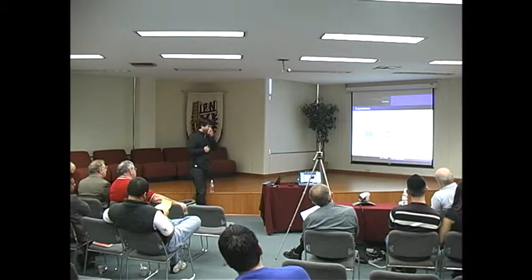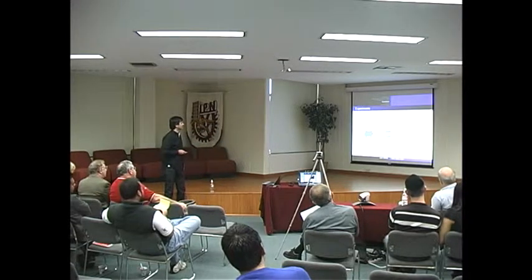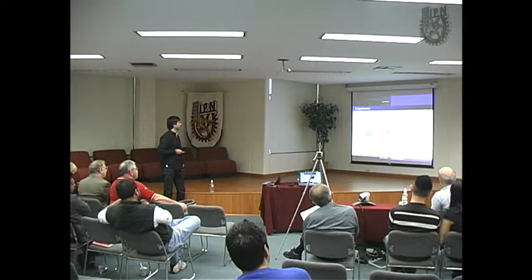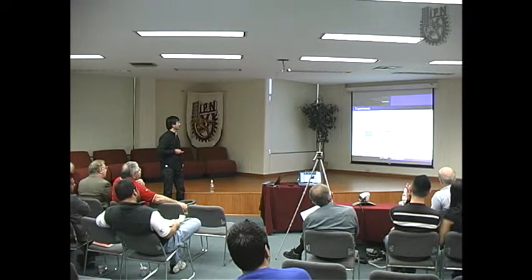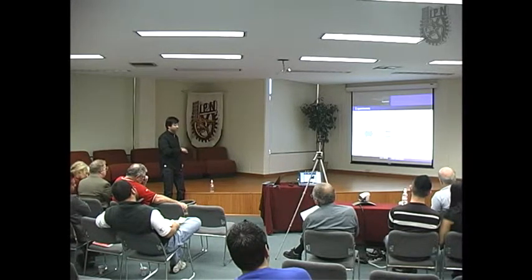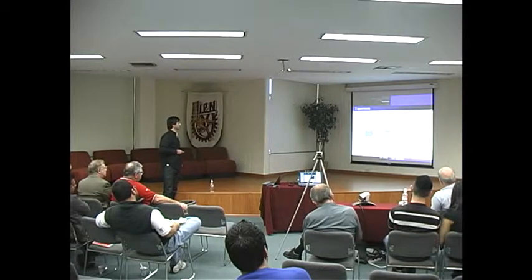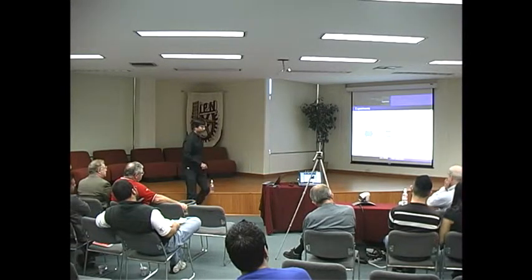So we have here some experimental tests in order to check the theory. Here is a block diagram of the implementation. We have a boost converter, a PWM circuit, some sensors to achieve feedback, a data acquisition board, and a PC running Simulink and MATLAB in order to implement the experiment in real time.